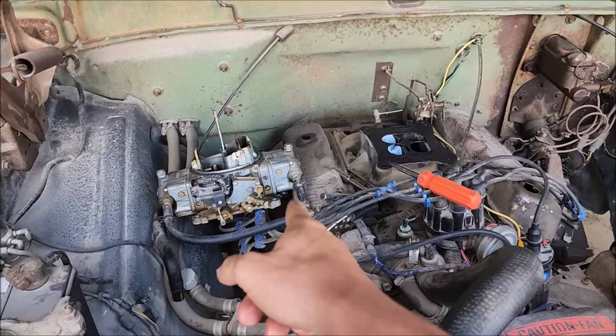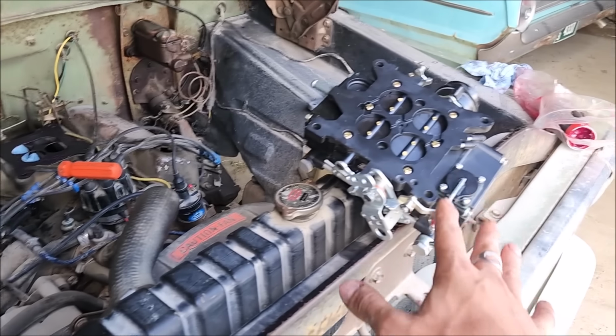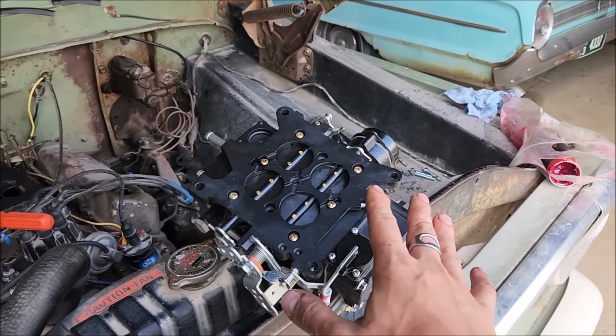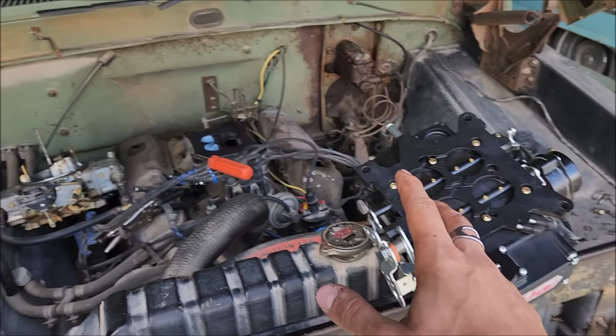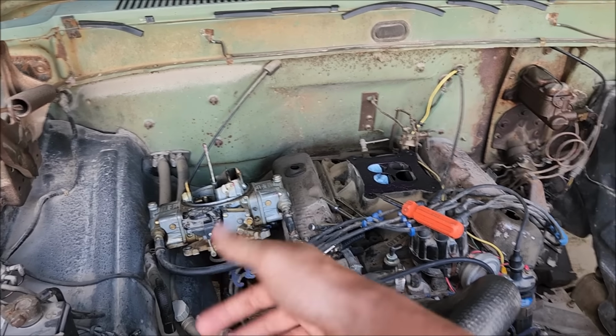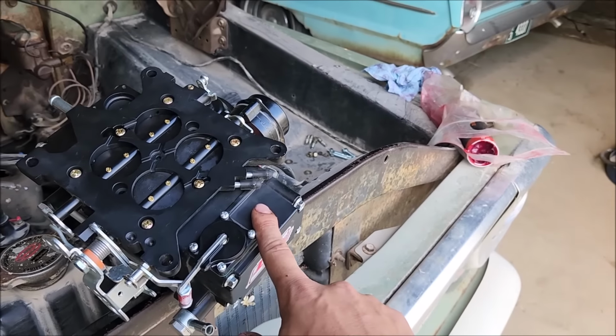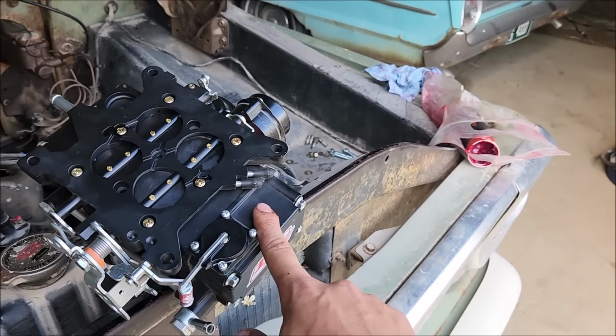Now, when you have your carburetor off, it is a fine time to look at your vacuum caps. The vacuum caps from the factory are made of rubber. They don't last very long, and I highly recommend the nylon vacuum caps like I have on this carburetor from any parts store, or I'll leave a link below. But as you can see here, after less than a year of this carburetor just being in my possession, the vacuum caps have cracked, and those would definitely manifest themselves as small anomalous vacuum leaks.